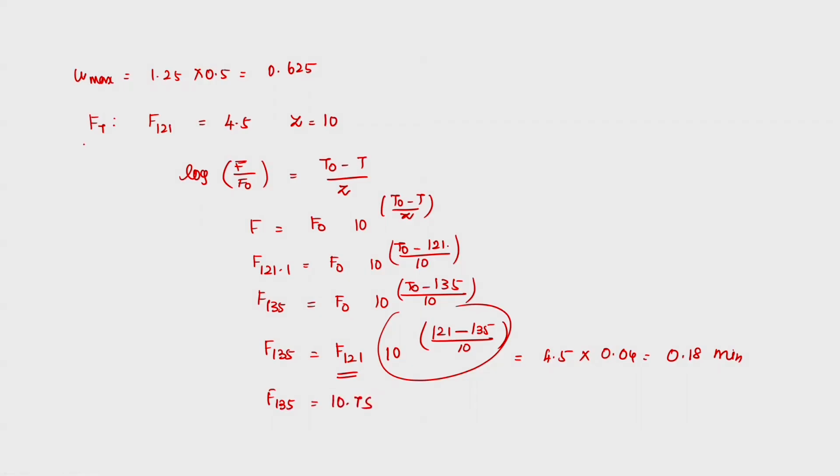So, I have calculated my Ft, I have calculated my U max. So, the length of the holding tube is nothing but Ft into U max, which is 10.7 into 0.625, which comes around 6.7 meters.